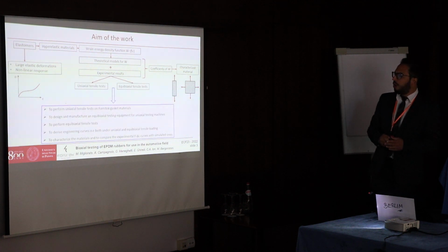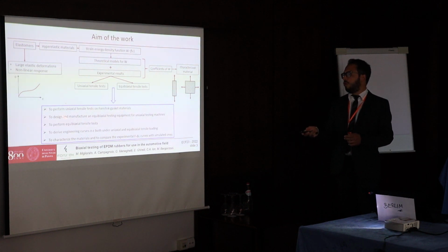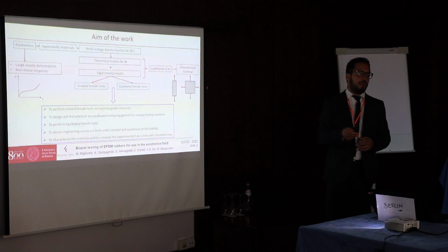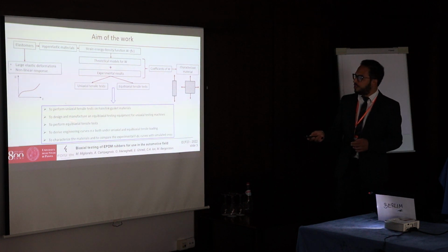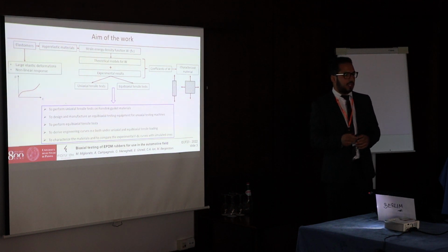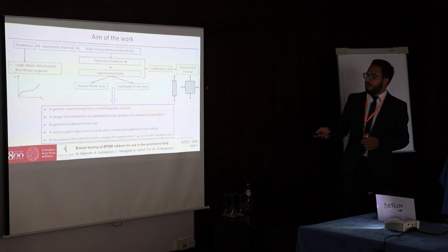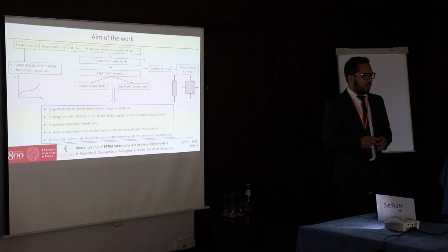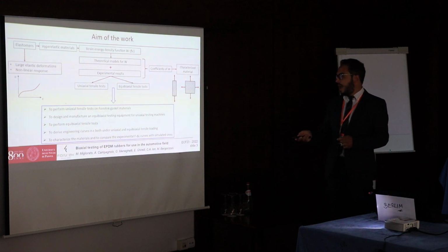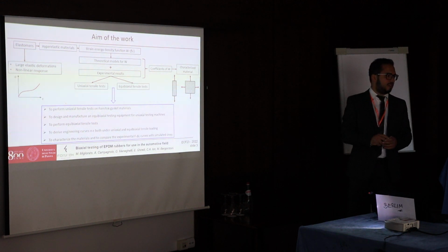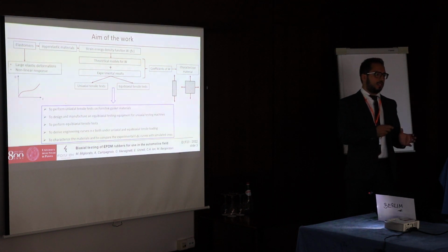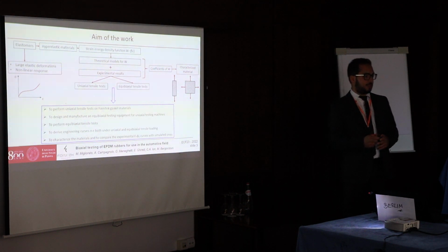So the aims of this work are to perform a uniaxial tensile test on materials adopted by Fornitec to manufacture seals, to design and manufacture a fixture, to perform equibiaxial tensile tests, to derive engineering stress-strain curves of the materials under both stress conditions, to characterize the materials in terms of strain energy density function, and to compare the results between finite element simulation and experimental results.